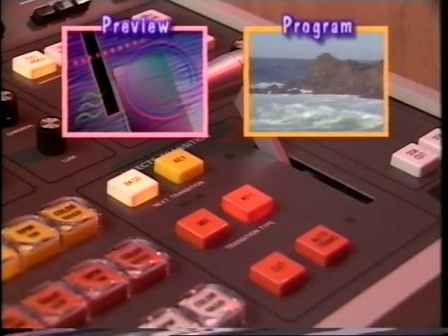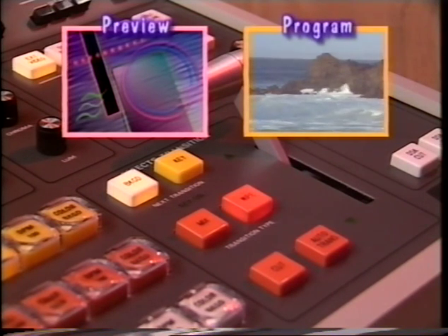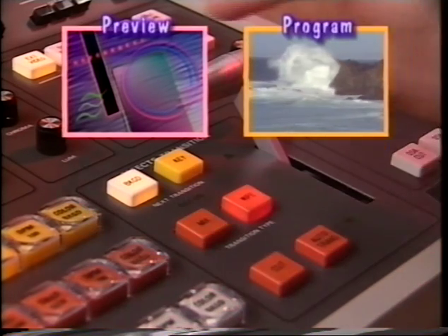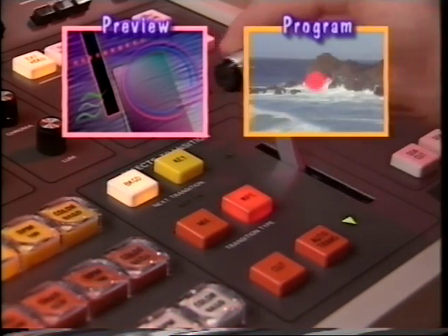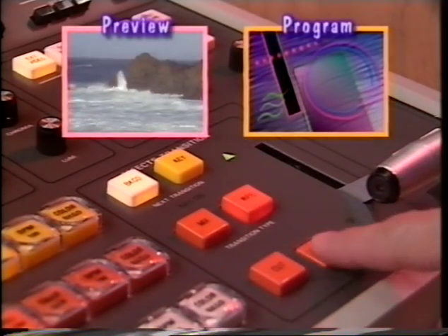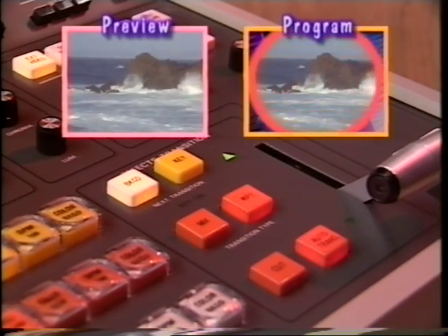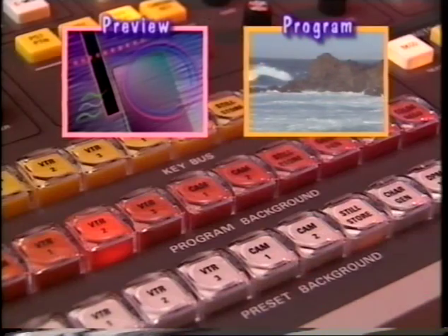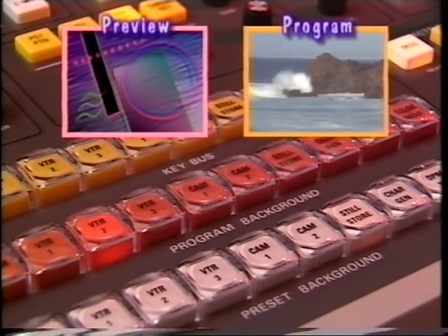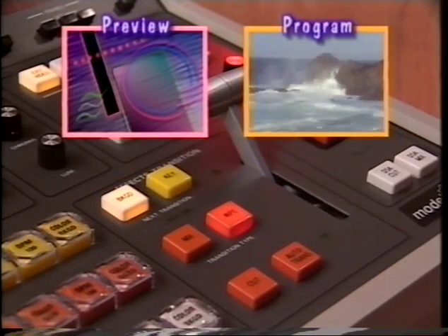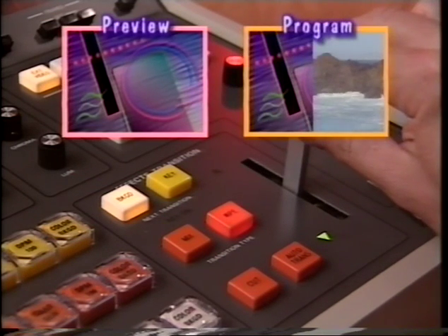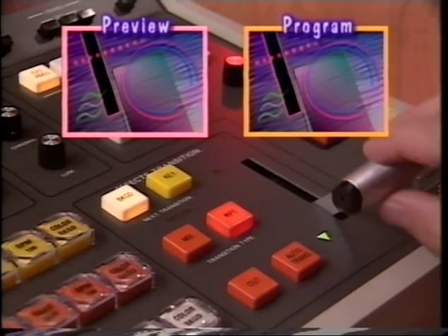The pattern will disappear from the preview monitor, but the wipe characteristics will still be present in the switcher. Once satisfied with the look of the wipe, you can move the lever arm to the opposite limit, or press Auto Trans to perform the wipe on air. At the end of the wipe, the two sources selected on the background buses will flip-flop. For a split screen effect, simply move the lever arm halfway between limits and pause before completing the transition.